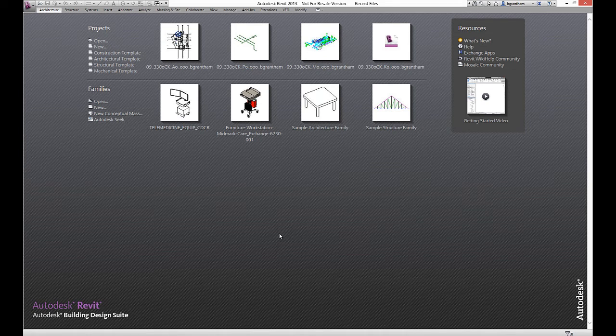So we're going to work on putting together a profile that we can leverage and putting a wall covering on a wall inside of Revit. There's a few different components that we need to create in order to make this happen properly for this project. The first thing that we're going to create is a profile. This profile is for a base that we're going to be placing at the bottom of a new wall type that's going to be inside of Revit.